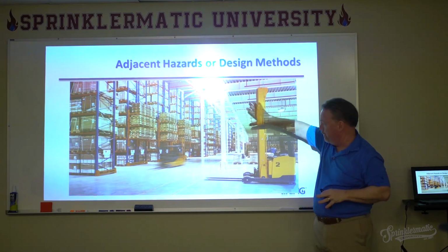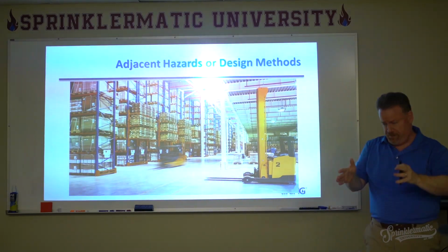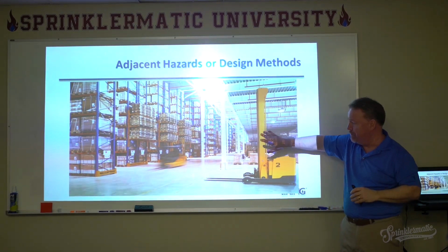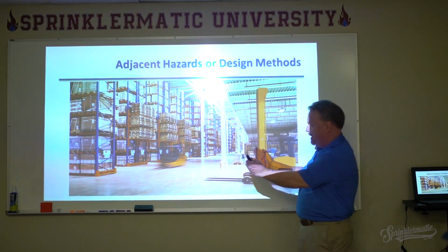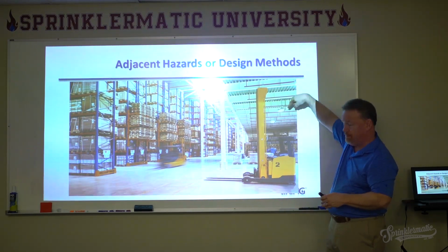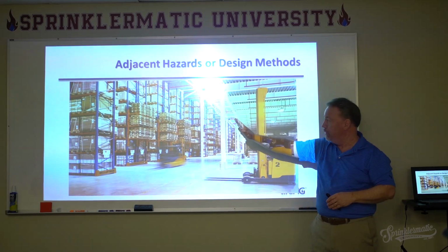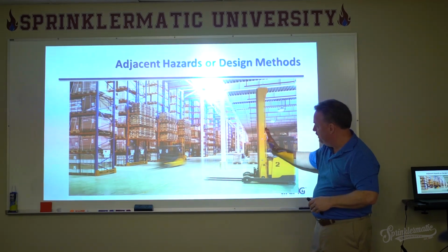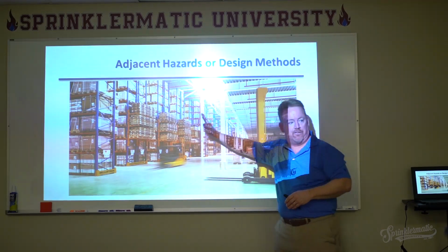You don't need quite as much water there as you do over here, but the standard requires you to design this separately, and separate this space either by changing the roof height or by having draft curtains up above, so that we don't have a fire operating sprinklers out in this design area, or vice versa.